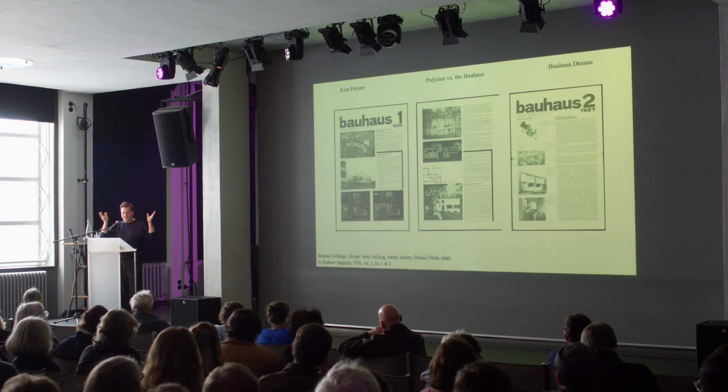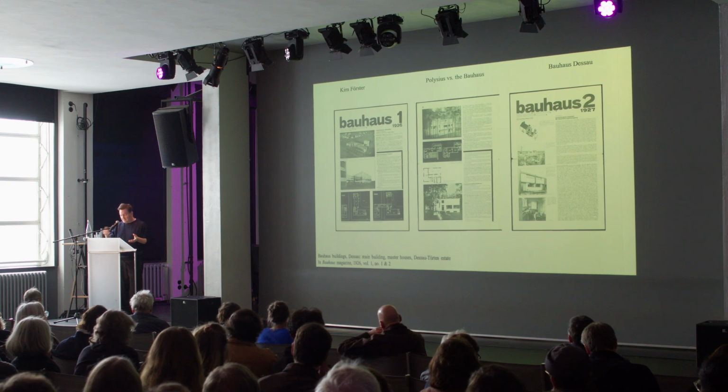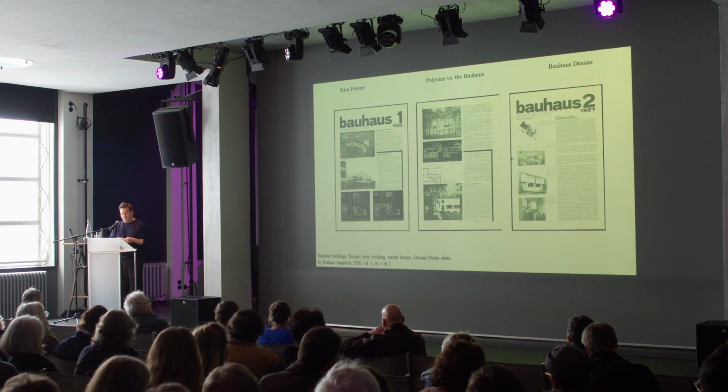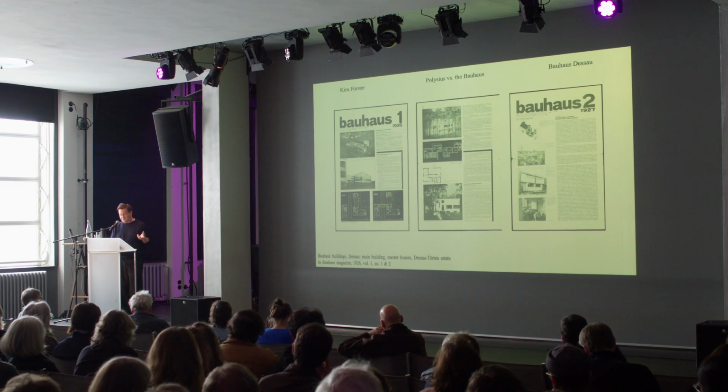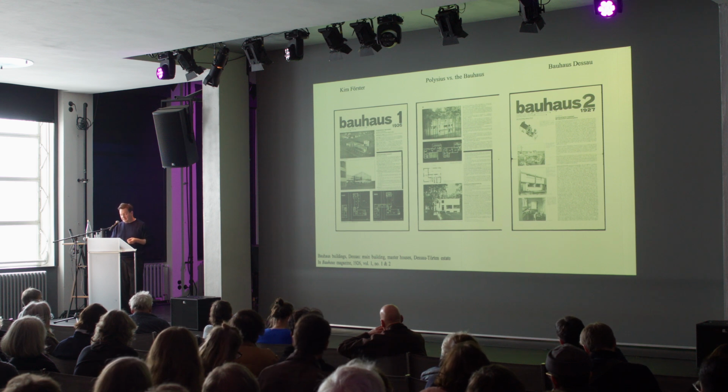And third, in Dessau-Törten, which some of you might see on Saturday, in this housing estate commissioned by the city of Dessau, the rationalization of the construction industry reached its most radical form. Aiming at mass production and cost reduction, Gropius developed a modular system of precast concrete elements, cantilevered columns and beams with load-bearing walls, again of cement-bonded slag concrete, and ceilings employing prefabricated reinforced concrete beams, the Betonrapidbalken, using an assembly line-style concrete machine, the Betoniermaschine, employing specialized work brigades.